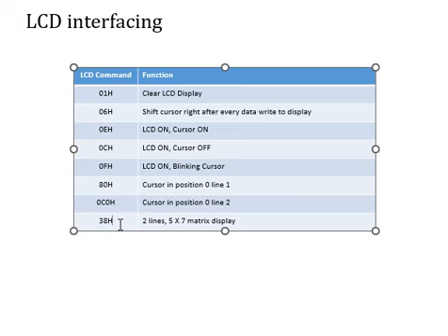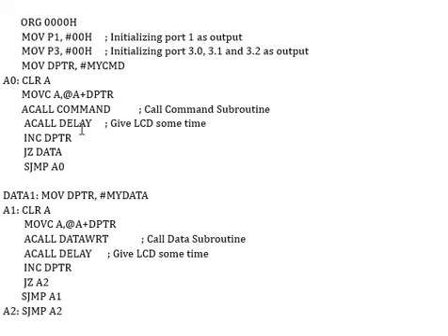And last one, 38 hex, it indicates that you are interested to initialize it as a 2-line LCD which is having 5 by 7 matrix display. Let us see how the program is done over there.